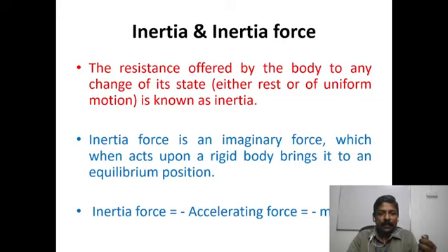Next one, inertia and inertia force. Inertia means the resistance offered by the body to any change of its state, either at rest or in uniform motion. Actually, it is a property due to which the body stays in its own state. Inertia force is an imaginary force which, when acted upon a rigid body, brings it to an equilibrium position. According to D'Alembert's principle, the inertia force and accelerating force are equal and opposite: inertia force is equal to minus accelerating force, which is equal to minus m into a.